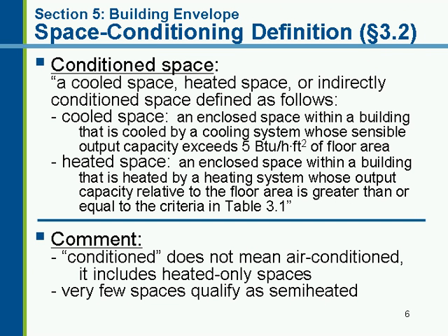Now let's talk some about conditioned space. Conditioned space does not mean air conditioned. It's a cooled space, a heated space, or an indirectly conditioned space. And these definitions are from Chapter 3, Section 3.2. When you're going through the document, here's a tip. Whenever you see a word in italics, that means that it's defined somewhere in Chapter 3. So flip to Chapter 3 and you can get more detailed information about what that term means and what it encompasses.